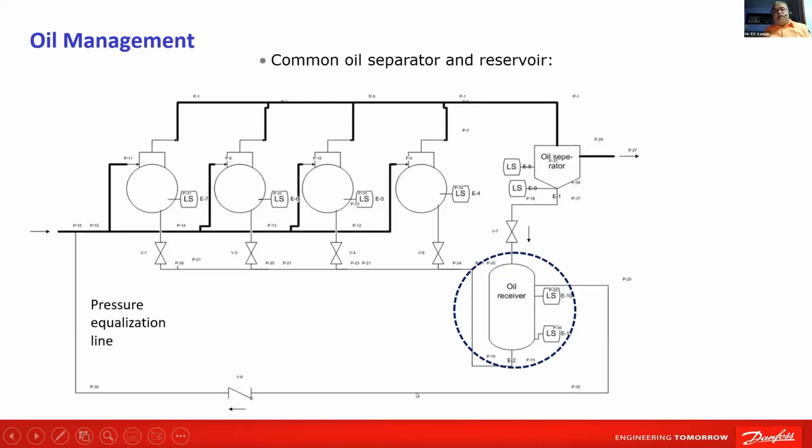There will be a pressure differential between this and this. Thank you for this question. We will need to have a control valve here to differentiate the pressure. Meaning, if the suction pressure is X, X plus something will be here, not the discharge pressure. Slightly more pressure than the suction pressure. Let's say 3-4 bar or 5 bar.